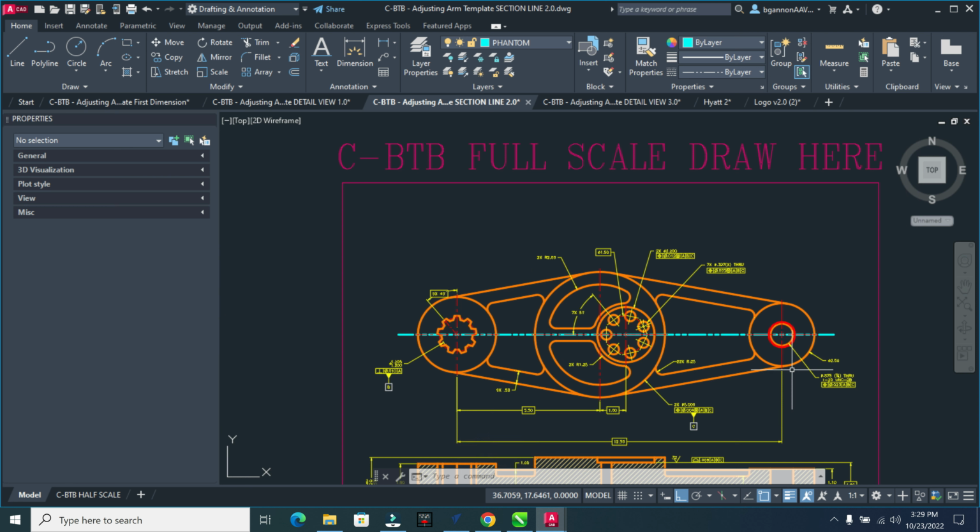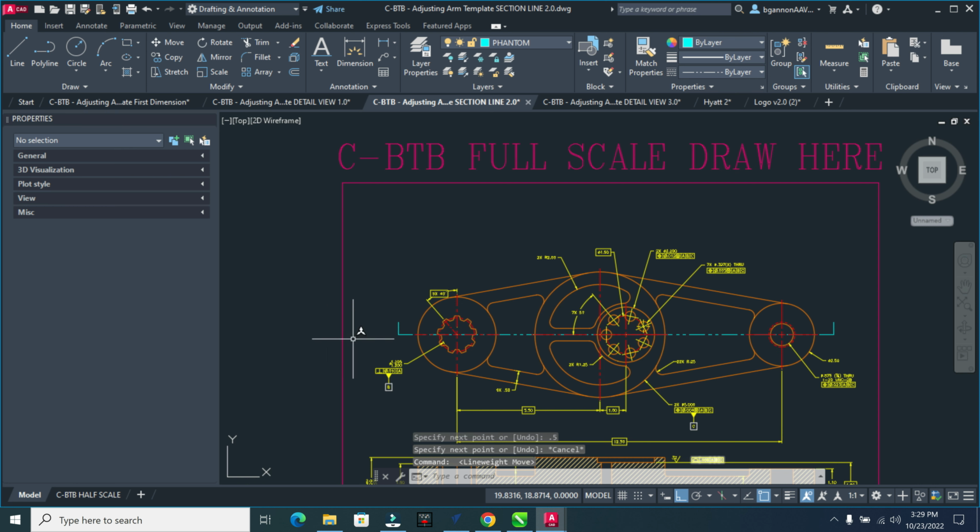That looks great. And then I'm going to draw simply up in that corner. I'm going to go up, and I'm going to do 0.5, enter. And let me do the same thing on this side. L, and then 0.5, and enter. And escape. All right, now I have my phantom line drawn. I'm going to turn off my line width display so I can see it a bit better.